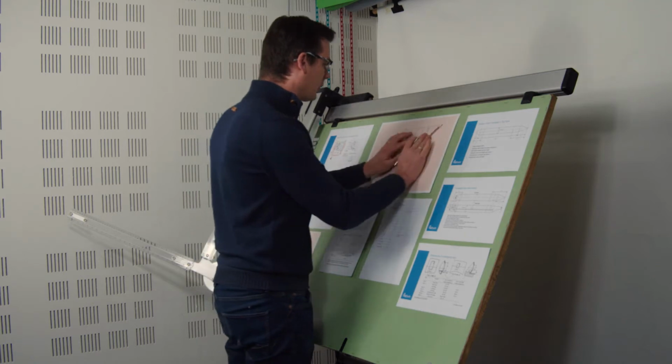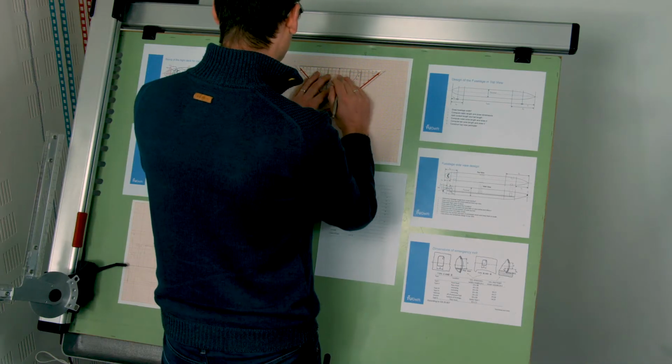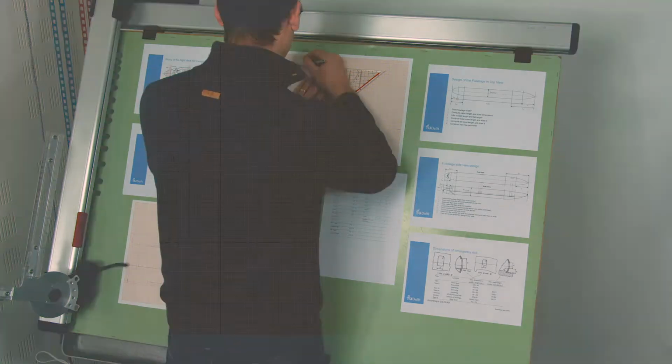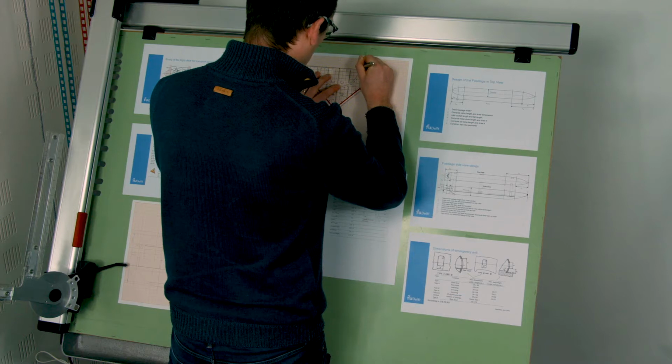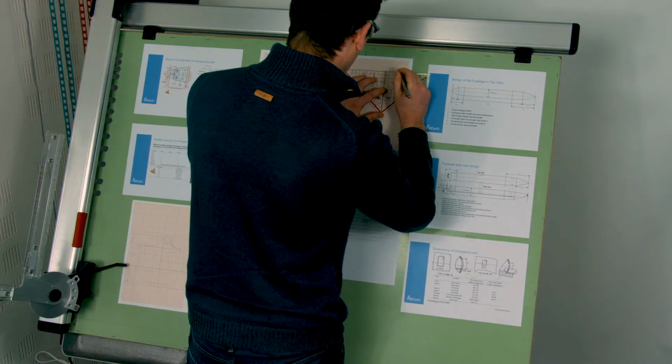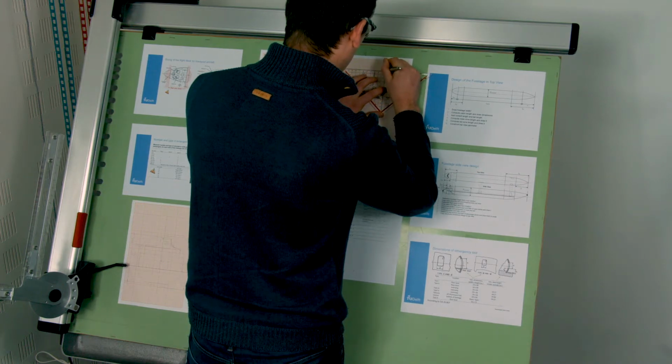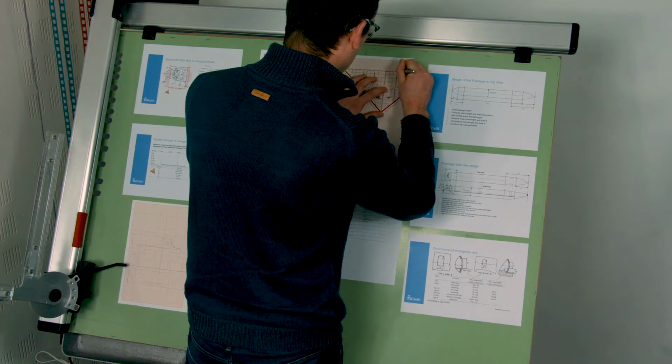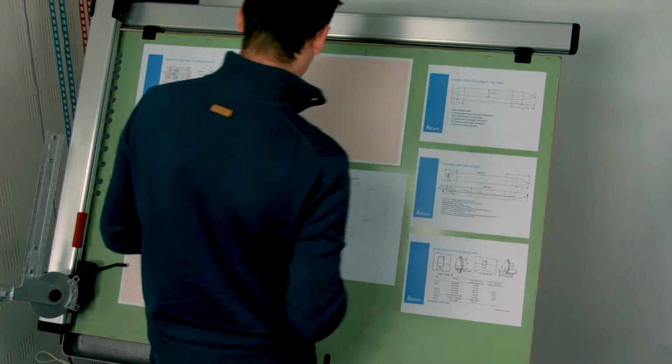I'm doing the same thing in the top view. Just drawing the center line there. Make sure it's straight with a dashed dotted line. It needs to be a little bit longer, because I already know that my fuselage is barely going to fit on there. Finally, also in the side view, which is also indicated as 30 millimeters from the top part of that box that you just drew.